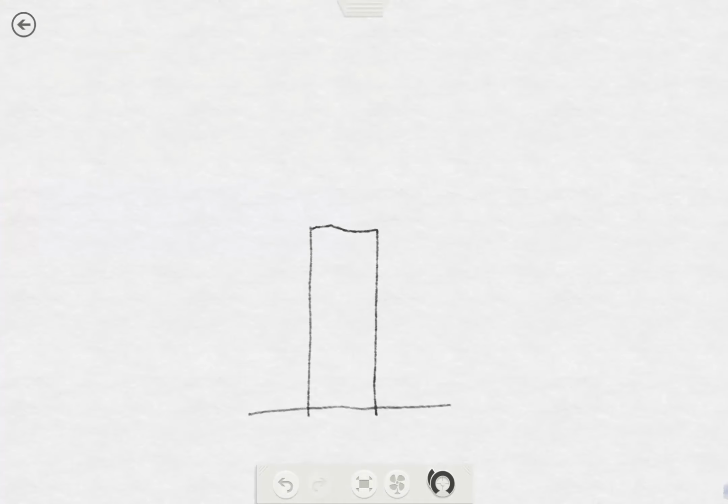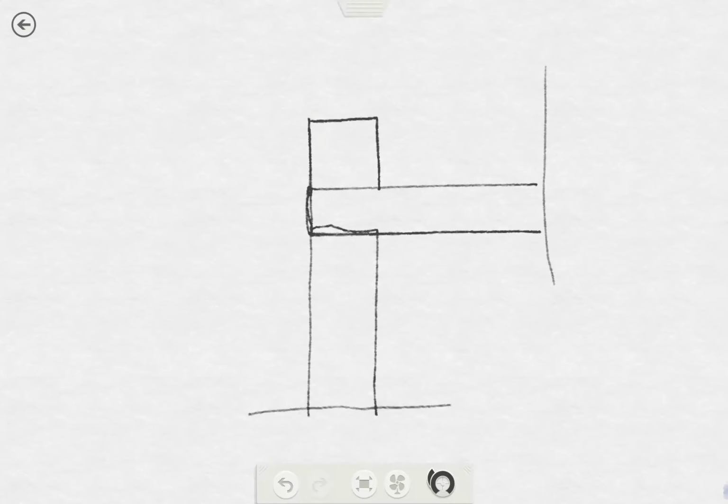We know that we have a structural slab here. So we have a concrete slab here. So this is concrete. But this is not correct, because if this is a roof, we always need a parapet here. We can have a flat roof, but we need a parapet to prevent people from falling down. So that's why we need a parapet. This is the main structure of the building.